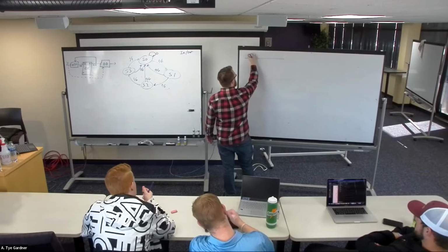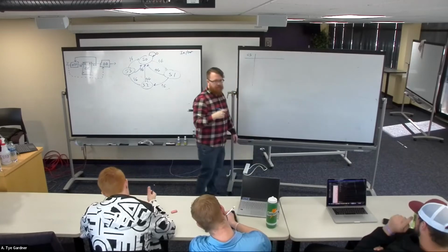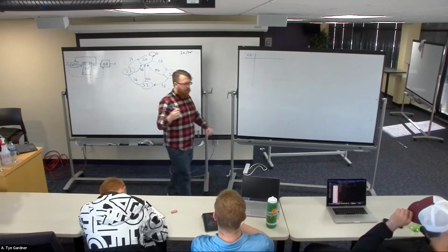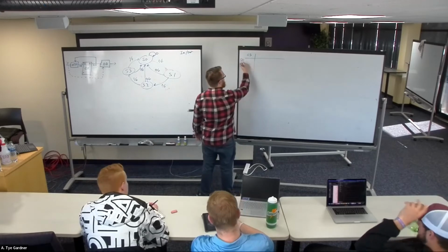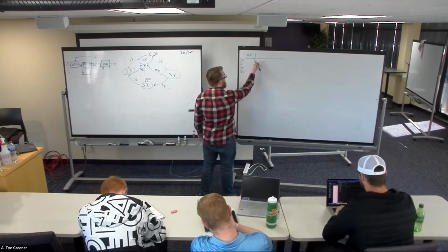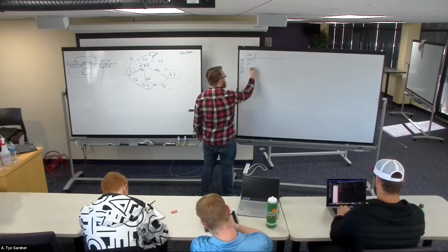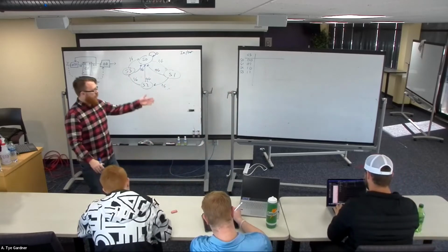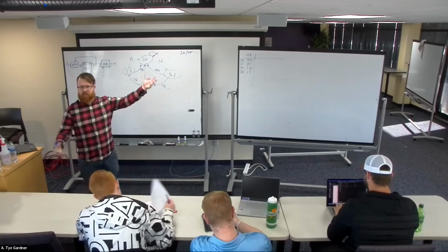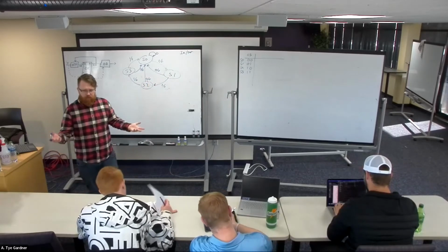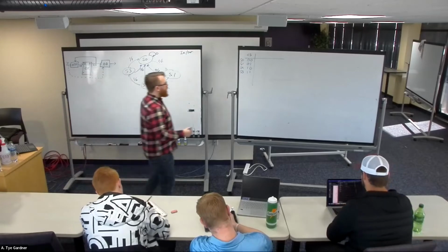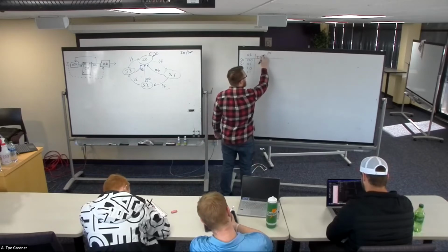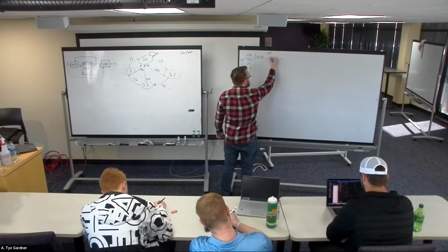And we do that by saying, this is my current state, right? The CS. And that's this signal coming out. That's how many bits I have. So keep that connection in mind. They're going to be S0, S1, S2, and S3, and we can assign them 00 state codes. That's just saying that these states have binary numbers associated with them, because that's all computers know, right? Computers only know zeros and ones. They don't know S's. Then my next state is going to be what happens based on my input. So if I is 0 or I is 1.